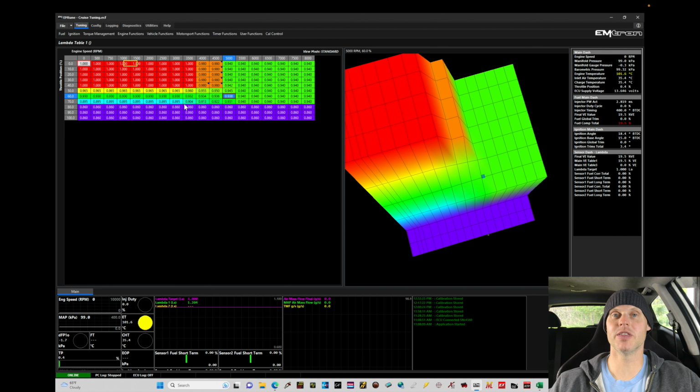We're going to be taking a look in this tutorial at dialing in our full throttle tuning on our low cam operation. So this is going to be non-VTEC, taking a look at dialing in our airflow model, fueling model, so the VE table, dialing in our spark timing, setting up our knock control, setting up and tuning our variable valve timing control. So we have a lot of things to unpack and discuss in this training module.